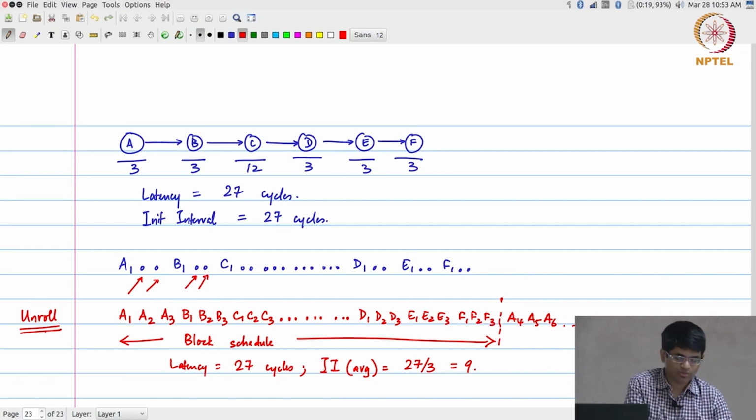Okay. So what we are going to do tomorrow is look at how we can rewrite this code in such a way that these dependencies could be shifted around a little bit and give us an initiation interval of 6, which in this case is the best possible because you have 6 steps inside the for loop. So you can't really look for an initiation interval less than 6. The same concept can then be applied to the entire function level in hardware, and we will look at that in the context of the FFT code and see how that can be used to bring down the latency.